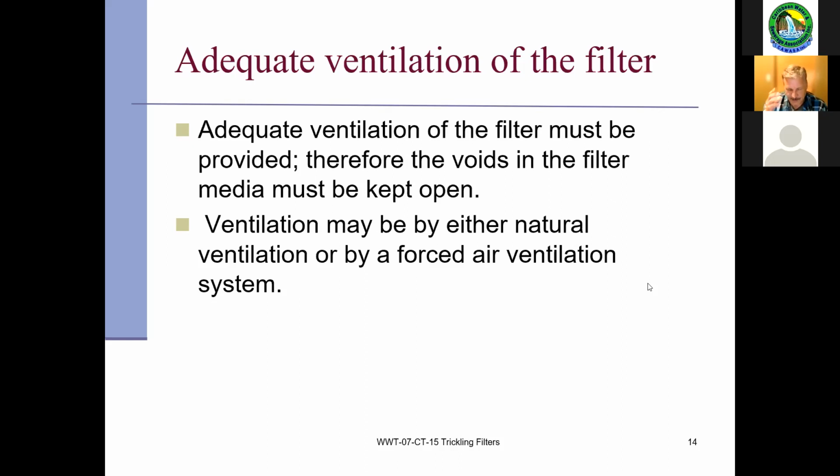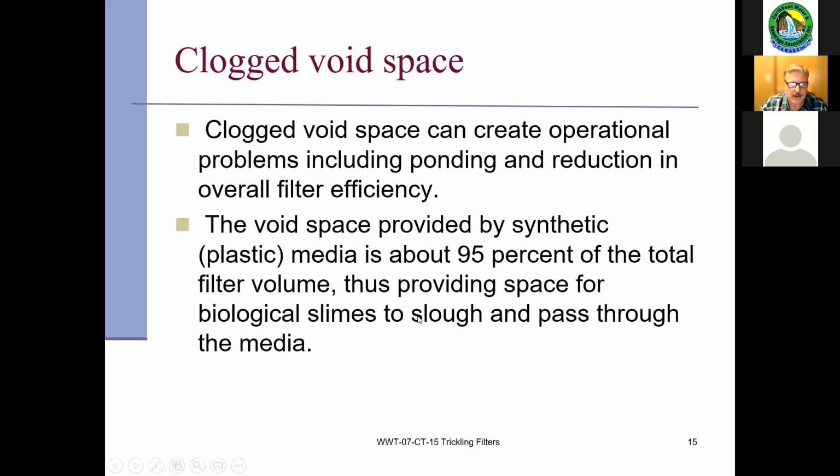So try and keep that in mind when you're looking at things, especially with trickling filters, where it sounds like nobody has any dealings with them. You haven't seen them before. It's just a biological tank that needs somewhere for the media to grow, so you have a biofilm on it. It needs food and it needs air.